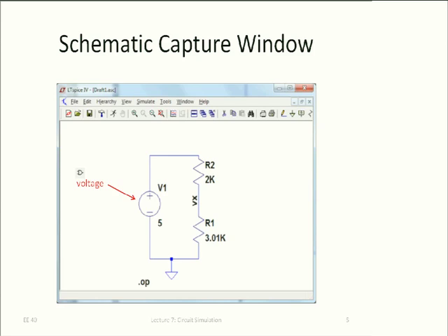So there is another symbol that is further on that board. It looks actually like a digital gate. We'll see that symbol later. But if you click on it, you don't get a digital gate, but you get some kind of a pop-up window, and that has the names of a lot of elements that you could also add. And one of them is called voltage. That's the one you want. Okay? Then you get this element here also on the schematic diagram. Then you need to click on that other tool. Then you can go and make all the wiring, right? So that it's all wired together.